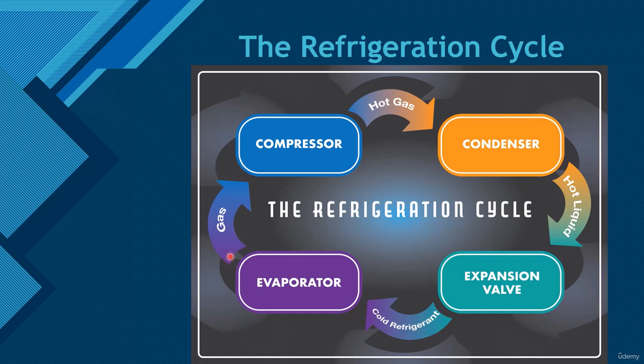And then that heat is in this cold vapor gas, and it's compressed into a hot gas, which enters the condenser, and that's where the heat from the home is released and blown out the top of that fan that you see out there. So that heat that you feel is actually the heat that's coming from the inside of your home.